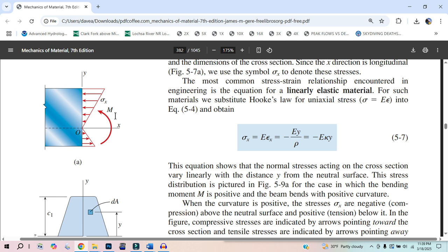Now, it's not a dynamics problem. If we do have a net axial force, it doesn't mean it's moving across the universe. It just means that it's stretching out while you're bending it. And that's the thing that will get related, but it's just like how much can you take at one point? But you could bend this beam with your two fingers, or like a ruler on both sides, and while you're bending it, try to pull it as well. Like you could physically do that, and you will have a net tension.